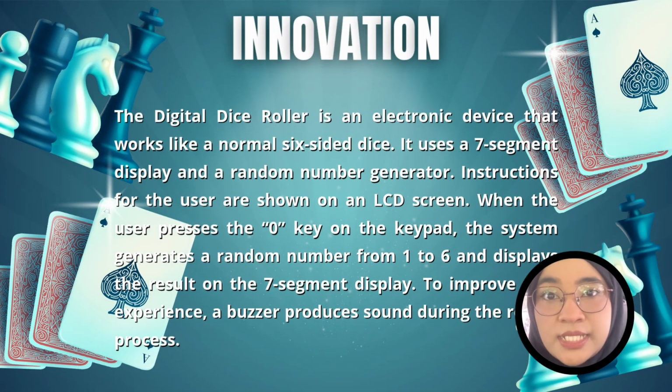Innovation. The digital dice roller is an electronic device that works like a normal 6-sided dice. It uses a 7-segment display and a random number generator. Instructions for the user are shown on an LCD screen. When the user presses the 0 key on the keypad, the system generates a random number from 1 to 6 and displays the result on the 7-segment display. To improve user experience, a buzzer produces sound during the rolling process.